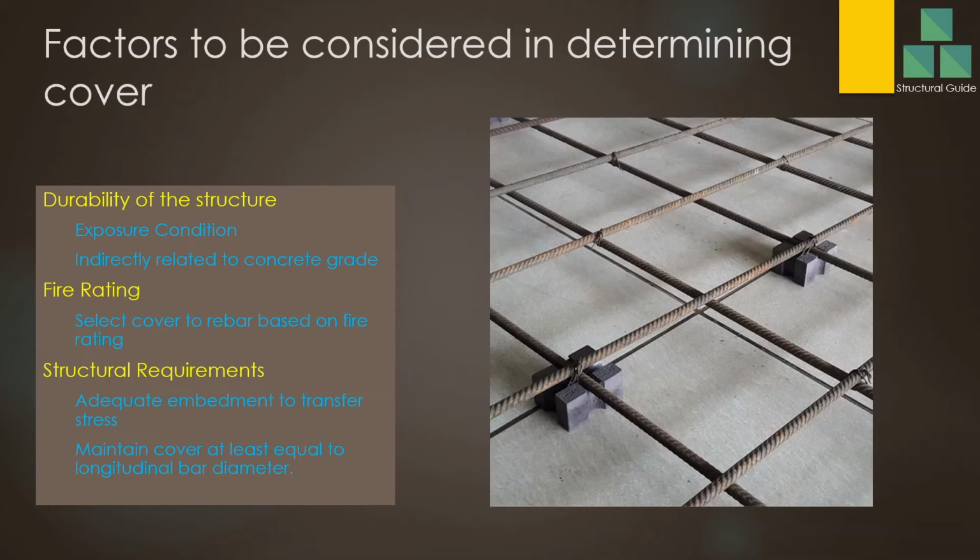In addition, there is an indirect relationship between cover to the reinforcement and the concrete grade. When we specify the concrete grade, it is somewhat correlated with the cover. Especially when we consider the exposure class together with cover, we consider it when finalizing concrete grades, minimum cement contents, and water cement ratios.